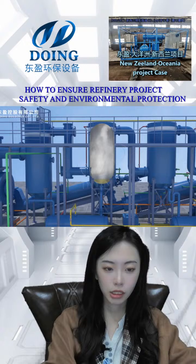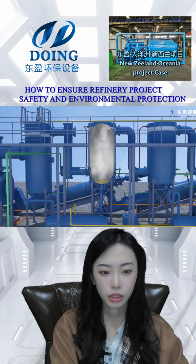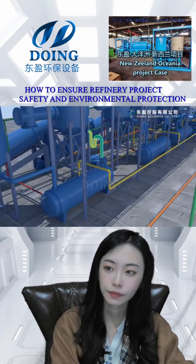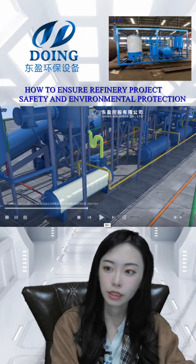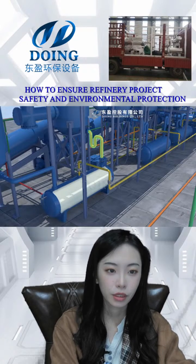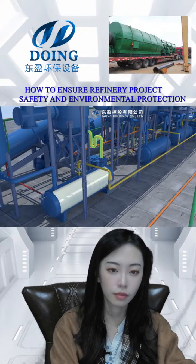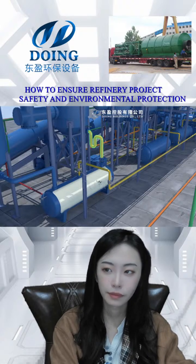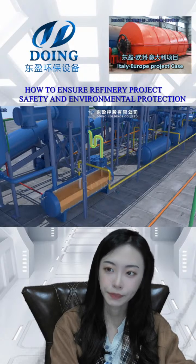The cover is also a water jacket, that has a condensation effect. And this is the temporary oil. The oil will temporarily stay here. And you can see here, this is the U-tube, to balance the pressure and to prevent the oil gas from entering this oil tank while we pump it. This is an oil storage tank of 2 tons.